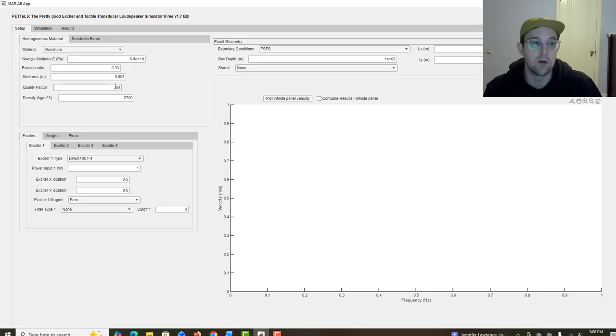It's a property of a mode or of a peak in a frequency response. So I can be extremely reductive and say all of the modes in a structure are going to have the same quality factor, and it's based solely on the material, which sometimes is kind of true and is a better estimate than anything else I have available to me right now.